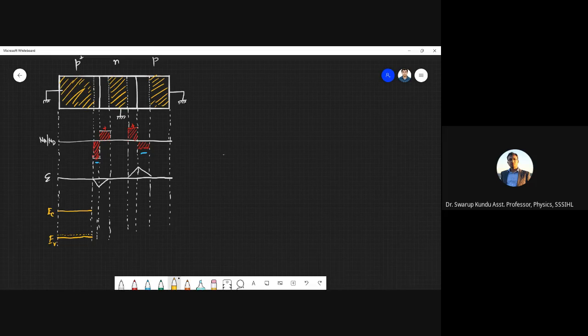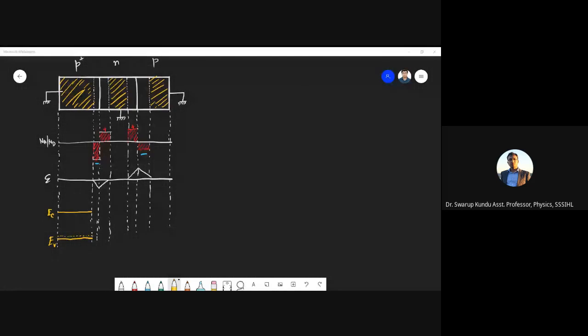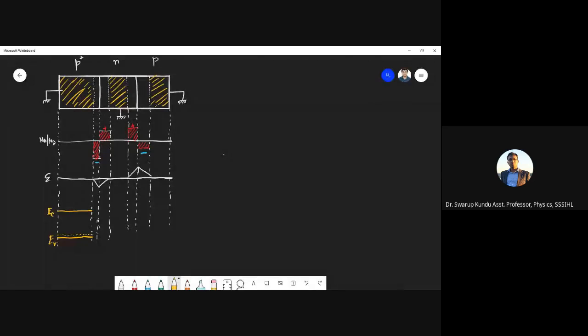The collector. So here the Fermi level is very close to your valence band. Now, as it is in thermal equilibrium and it's unbiased, basically all the three terminals are grounded, so Fermi level will be again constant throughout the device, right? So we got a reference now for Fermi level. So this is the Fermi energy level.